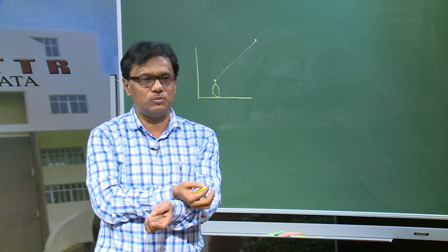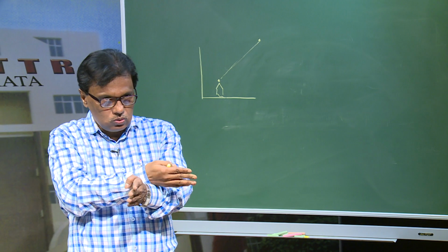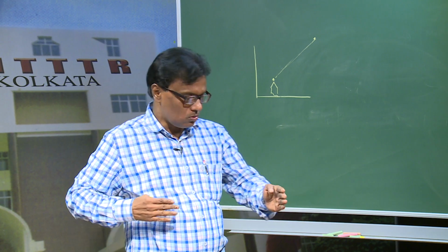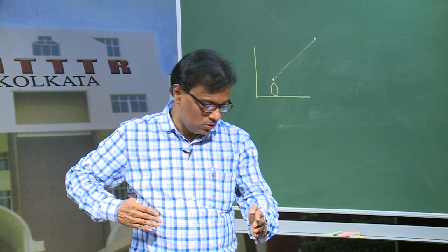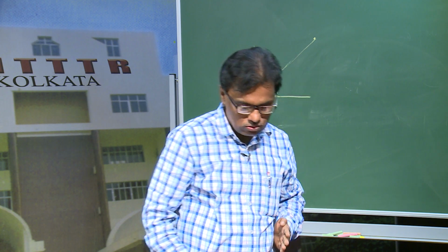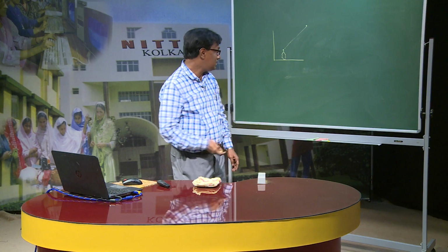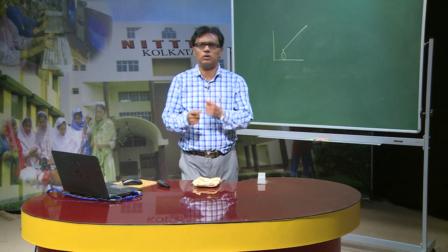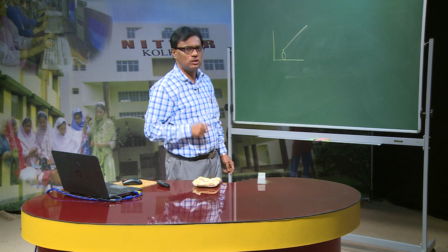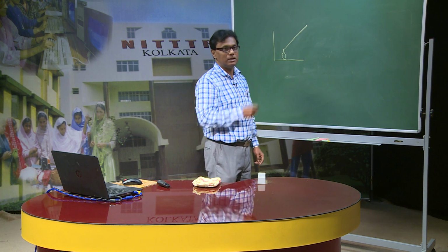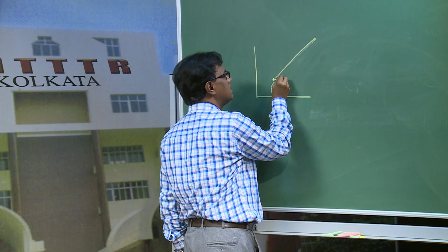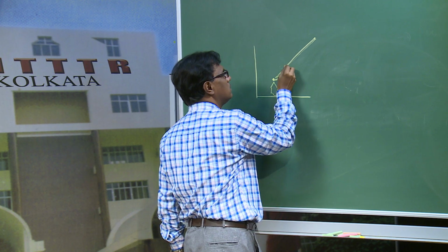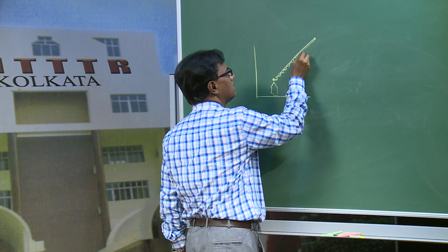Given the construction of the CNC machine, there are two perpendicular lead screws where a motor is connected at the end. So, my tool can go either this way or this way. So, how is this angle achieved? Angular movement of the tool tip is only possible with a combination of two perpendicular movements.